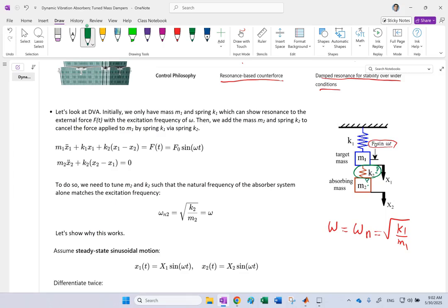So, first of all, before we answer that question, let's look at the equations of motion for the two DOF system. Because for the single DOF, it's very easy: M x double dot equals F naught sine omega t, and then minus K1 times X, or X1. But now that you have X1 and X2, for the object with mass M1, you have M1 times X1 double dot equals F of t, which you have, and then you have the spring forces, right?